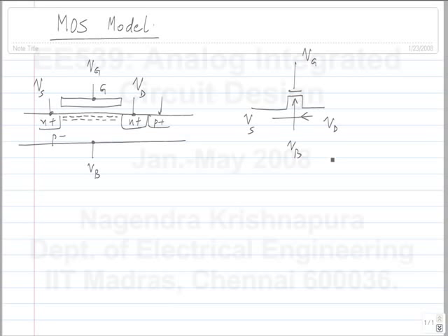So, you have to watch out for those conditions. Sometimes you design something and you simulate it and it behaves in a slightly unexpected way. One possible thing, among many hundreds of possibilities, is that the source has become the drain and the drain has become the source in some case. Okay. So, you have to watch out for that, because you typically identify one terminal as the source and do your mental analysis, but then perhaps the voltages in the circuit are the other way around and it is working in the opposite direction. Okay.